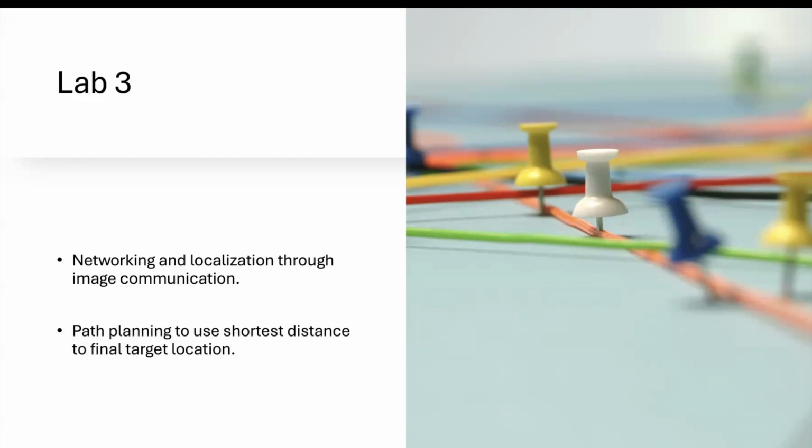To do this, we calculated a camera matrix with a focal length of around 500 to 504, and a specific distortion coefficient to ensure that there was a pixel-to-centimeter measurement and that these were being converted with as much accuracy as possible.